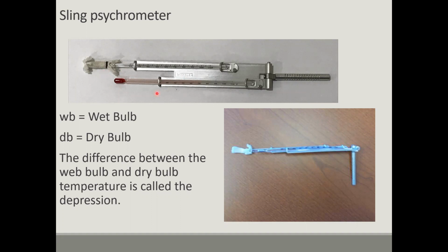So now we have what we call a dry bulb temperature and a wet bulb temperature. This starts to become important when we pick our air conditioning equipment, but we're going to be talking about latent loads and wet bulbs and dry bulbs and coincident wet bulbs. This is what it all comes back to. If I were to go spin this thing in certain conditions, I'm going to have a dry bulb and a wet bulb. If I know two properties of air, I can tell you anything about it.